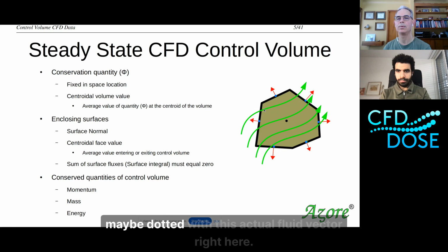So now let's look at a little bit more complicated control volume. Here I have a control volume. We have our box, and we have some sort of slotted system. Since we're talking about CFD tools, a fluid is entering the slot here. It passes through this slotted system, and then it exits here. We know a little bit of information about mass flow. Mass flow over here is a combination of the density of the fluid, perhaps the velocity of the fluid right here, and the area.